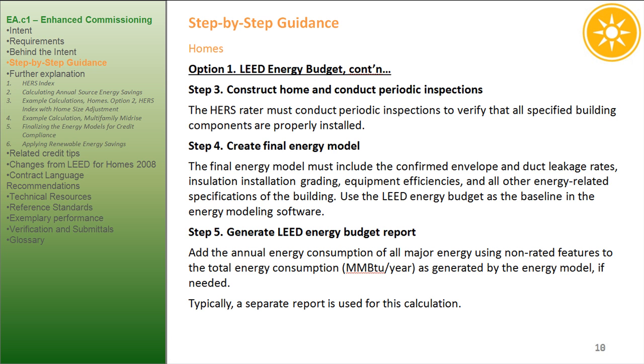Step 4. Create final energy model. The final energy model must include the confirmed envelope and duct leakage rates, insulation installation grading, equipment efficiencies, and all other energy-related specifications of the building. Use the LEED energy budget as the baseline in the energy modeling software.